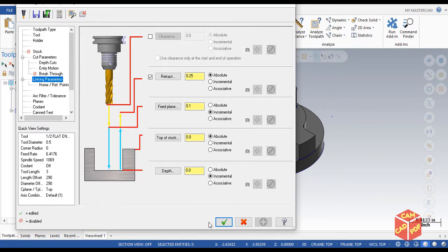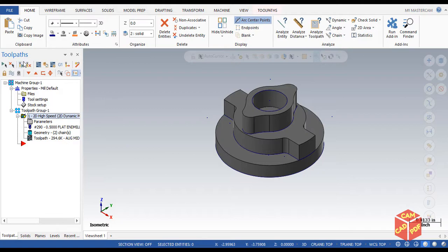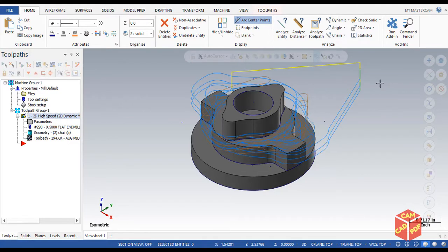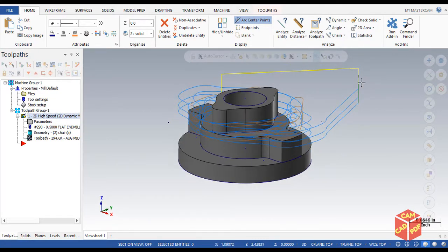So clearly if we see generate our toolpath, Alt T, first of all it's starting from 2 inch away, which we don't want right now. I just did for absolute distance, approach distance for example.